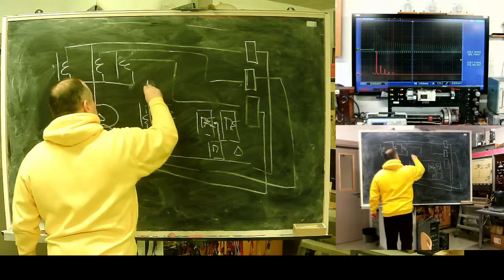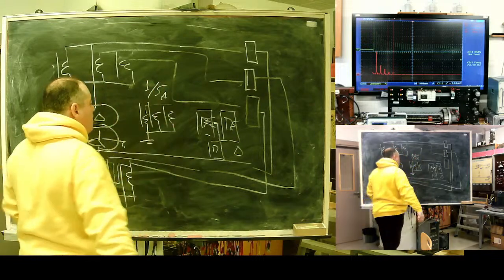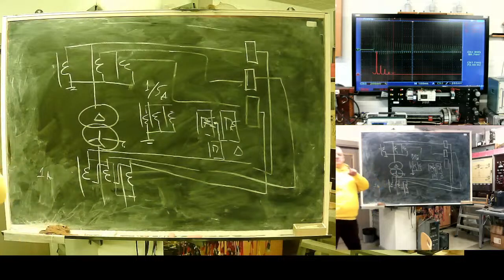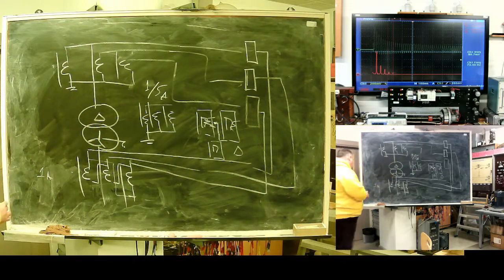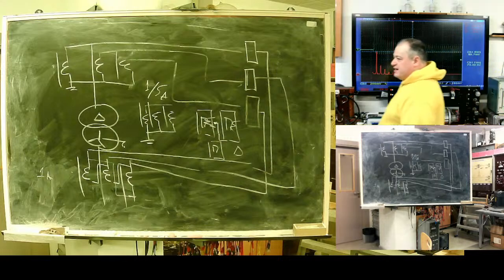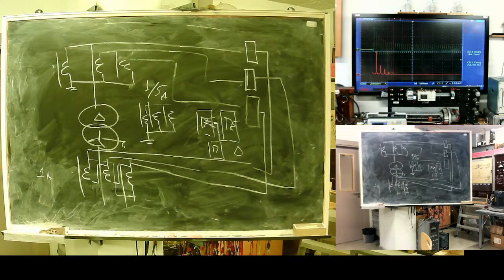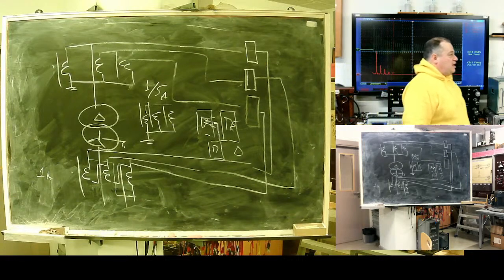Interim transformers 1 to 5 amps, with adjustable transformation ratio. It's done because the transformation ratio of this transformer is adjustable. So in previous years, it's still very rare design, very rare in new projects, but sometimes this build-up with interim transformers appears.